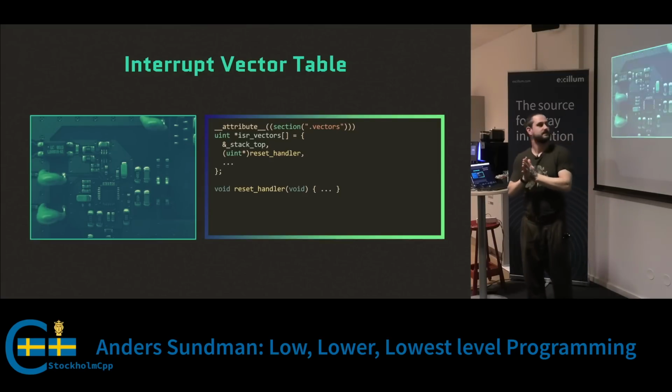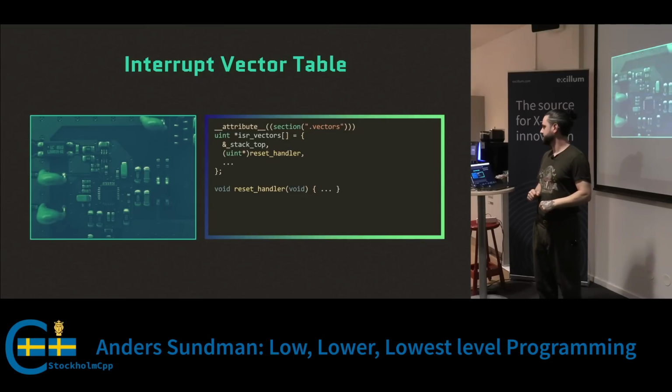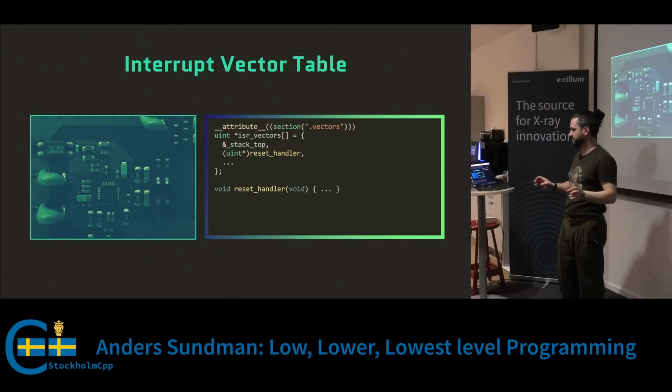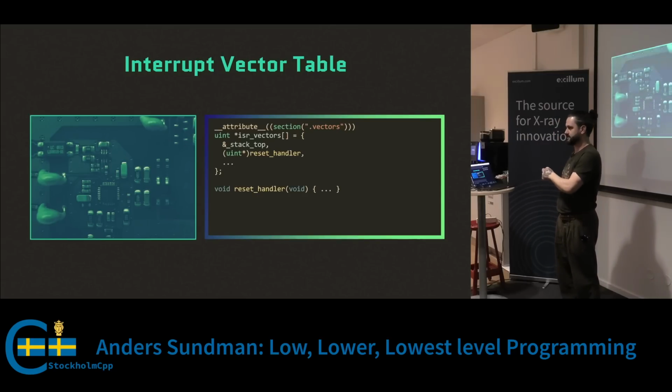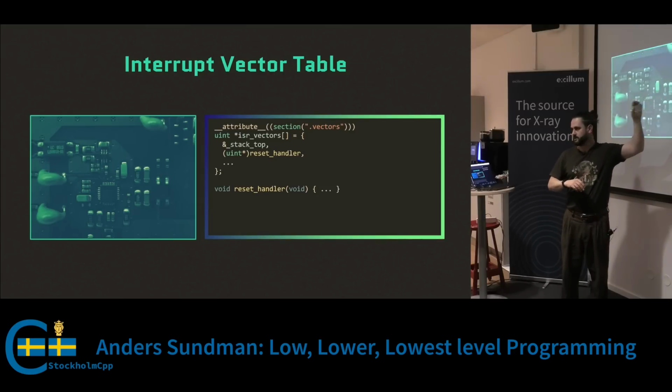Let's first decorate it a bit. This is a way you can make sure that you get a handle you can use in your linker scripts. So you can decorate functions. I said before that sometimes you want the text segment in Flash, sometimes you want it in RAM. This is a tricky way you can do it if you want to have a little bit of both. Sometimes you want a really fast function, or you want to be able to mutate the function. Then you can do something like that with some functions, like a RAM function, and put the RAM functions in RAM and the other functions in text.